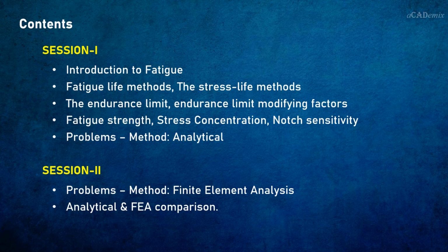In the first session, we shall go through the details of fatigue life methods, endurance limit modifying factors, fatigue strength, stress concentration factor, notch sensitivity, etc. Some basic problems related to fatigue life evaluation shall be discussed with analytical solutions. In the second session, we shall go through the numerical solution of the same problems with the finite element analysis method and the comparison of analytical and FEA methods.